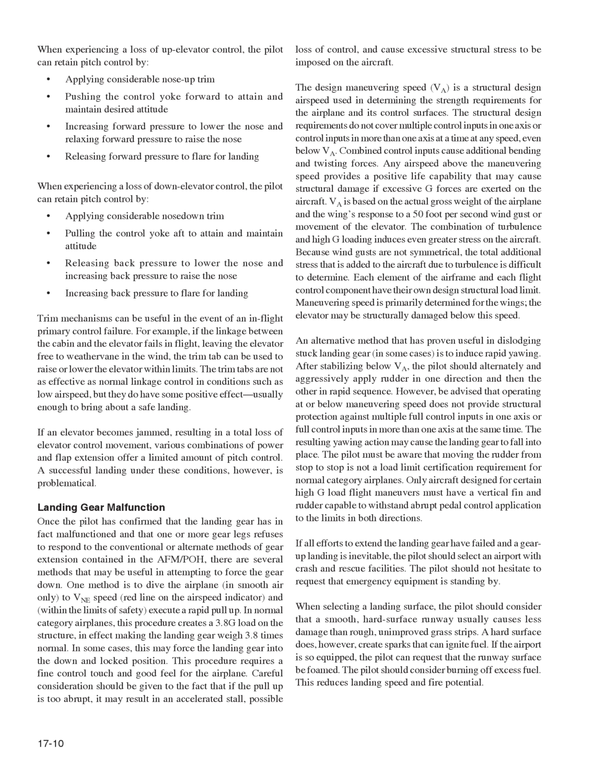If an elevator becomes jammed, resulting in a total loss of elevator control movement, various combinations of power and flap extension offer a limited amount of pitch control. A successful landing under these conditions, however, is problematical.